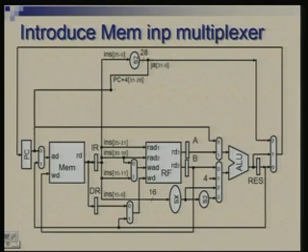For that we need to collapse multiple components onto the same thing, and with the help of multiplexers we are able to feed different inputs to those resources at different times, and then registers were introduced to break the time interval. So, the time interval gets broken into multiple clock cycles, and now the paths which need to be considered for delay analysis are much shorter paths.